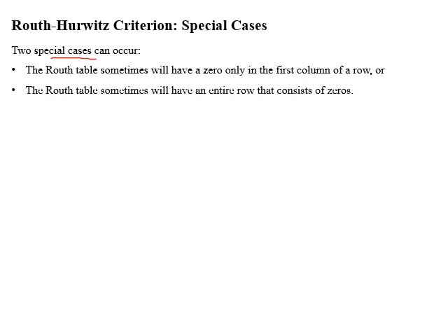First case we have while computing the Routh table is when 0 occurs in first column of the Routh table. As we know that element of first column is used in calculation of upcoming rows, so we will study how to avoid this and get the result about the stability of a system. Second case we have is when an entire row of zeros occur in the Routh table.